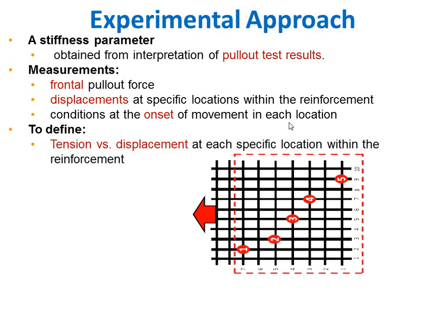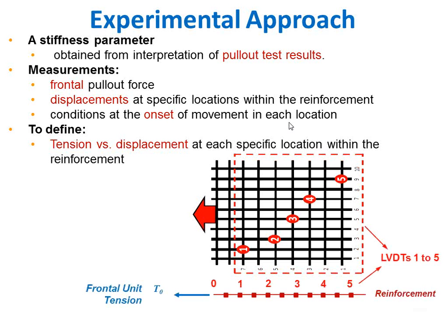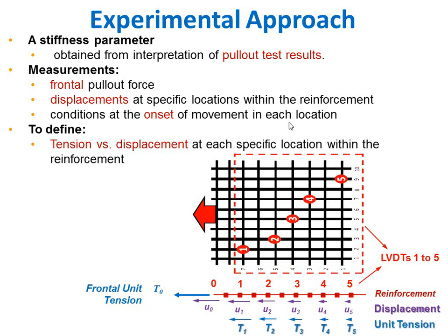So this is our reinforcement, and these are telltales. This is under confinement, and we're applying this load and monitoring the displacements at different points. So this is a cross view, this is a plan view. We're applying the frontal tension, and then we're going to monitor the displacement at different points. We do not measure the unit tension, we infer it in each one of those points. And this is the test that we're going to do.